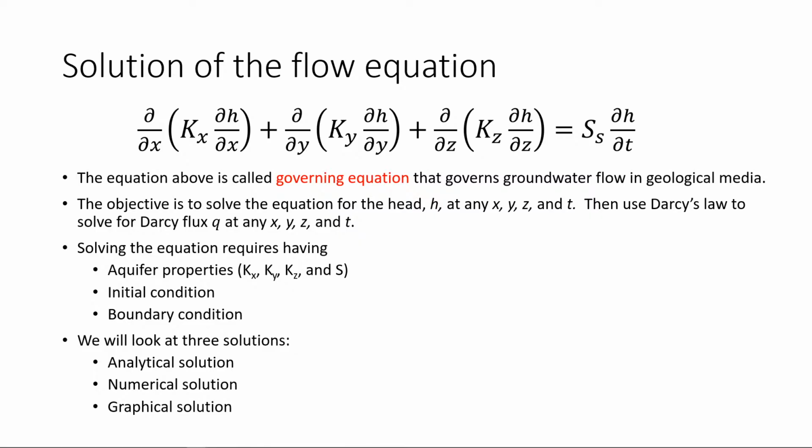So we saw this equation, and this equation has no analytical solution. Whatever you learned in a calculus course or differential equation course, you cannot apply here, because there's no analytical solution for it. We need to solve this numerically. That's exactly what MODFLOW is doing. MODFLOW, which we will be using later, solves this equation numerically, or something that looks similar to this equation, because it has some other source and sink terms and things like that.